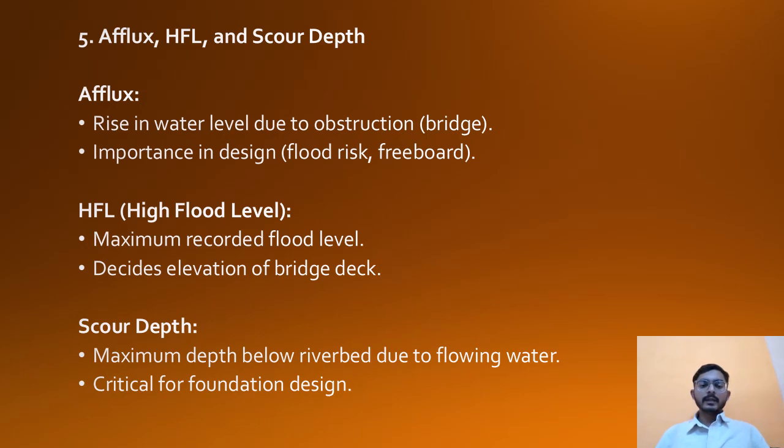And what is scour depth? It is the maximum depth below the riverbed due to flowing water. This is the depth which should be seen before construction, at what level water is flowing. The depth in the valleys or rivers should be checked. It is critical for foundation design: what scour depth there is, and at what level the foundation should be designed. This should also be checked.